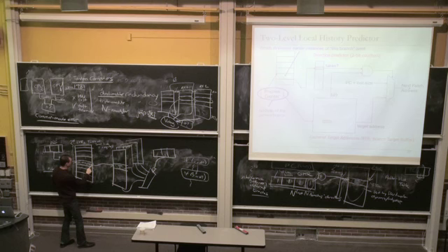So what do you mean? So the history can change, right? So this is telling you what is the local history for this branch. It could be 1, 1, 1, 1, 1, 1. The next time you see it could be 1, 1, 1, 1, 0. Right? So you really do not need different counters or different information.